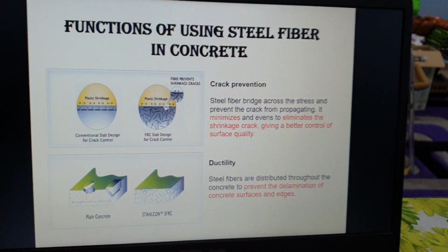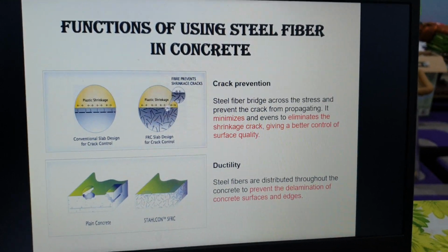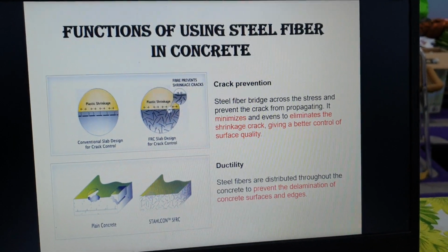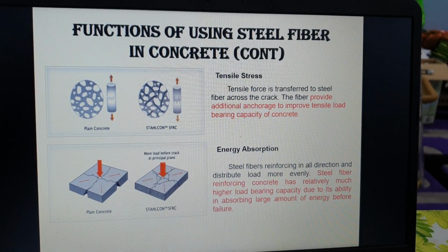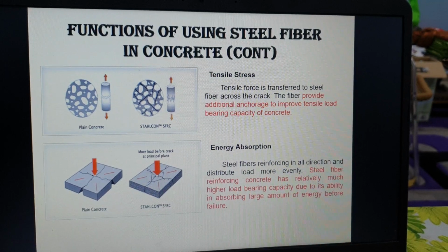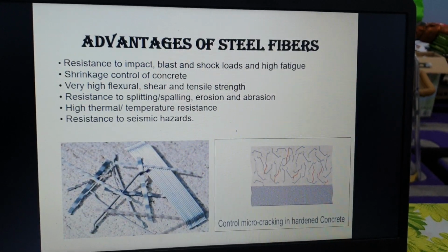Okay, the function of using steel fiber in concrete is to prevent cracks, and also for ductility. And of course it will give more in terms of tensile stress and also energy absorption.